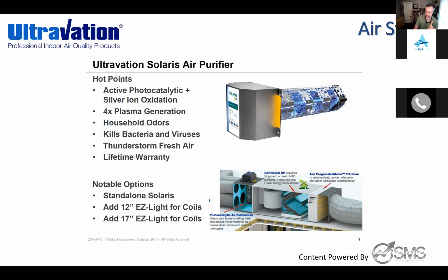But back to the ozone thing. This is technically not a zero ozone product because you aren't using carbon, that charcoal, to help absorb the byproduct. The one beauty of this product though, versus our Photomax as well, is we passed the same adjustability that we had into the Solaris. So we have a 4-inch adjustment range inside that ballast. We have a special dual band bulb, still 2-year life like our T3, but it's a special bulb. And we figured out a way to block the amount of PCO that is being generated.